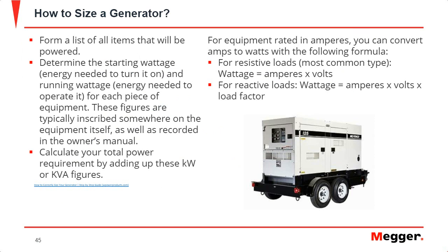A quick note here is, how would you size a generator? A lot of times you're out in the field, using generator power to power these primary injection test sets as you go and do a job. So here we just have a quick list of what you can do to size your generator properly. Basically, you want a list of all the items that are going to be powered with that, whether you're powering a single primary injection test set or different appliances.